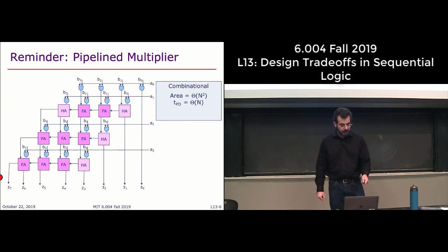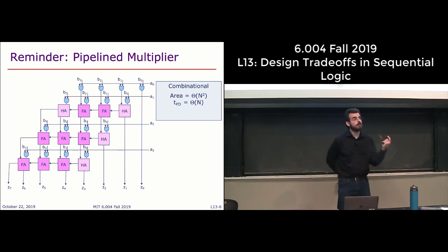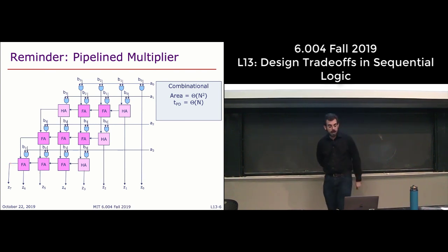So basically anything that comes from one of the top inputs and ends up at the bottom left output is going to have the maximum number of 1-bit adder blocks between it. And so here, if we just count, you have 4 blocks plus 2 plus 2. But if we generalize, you're going to have n blocks and then n minus 2 times 2, right?